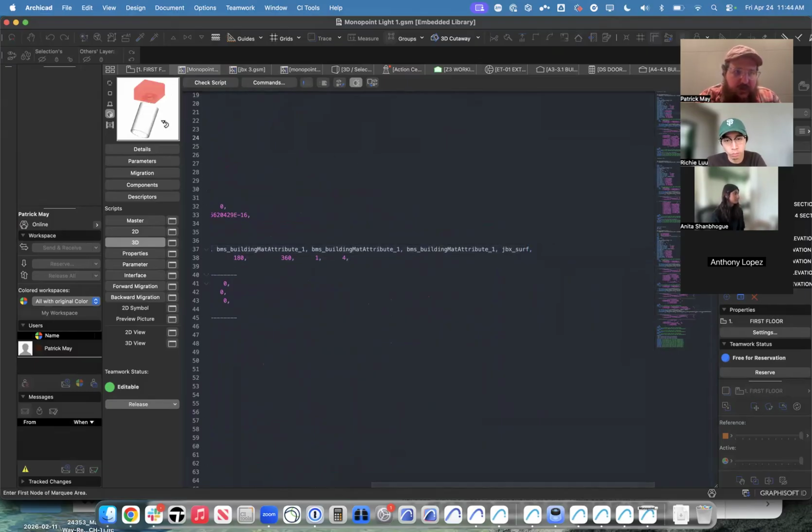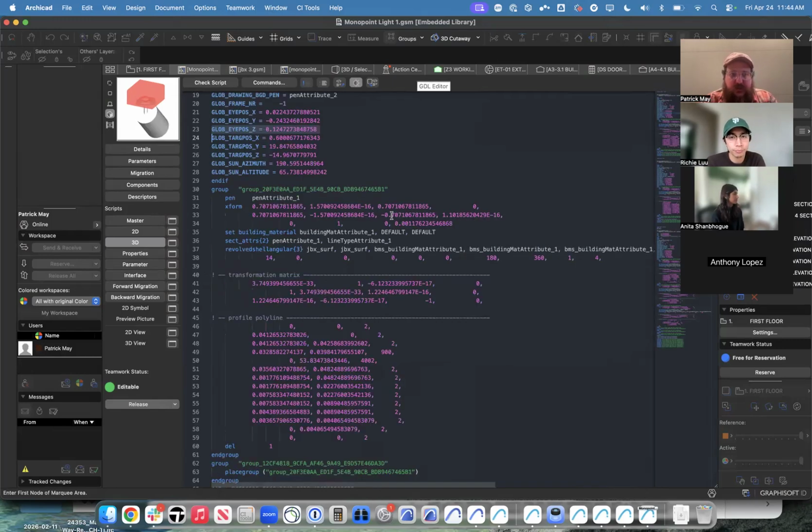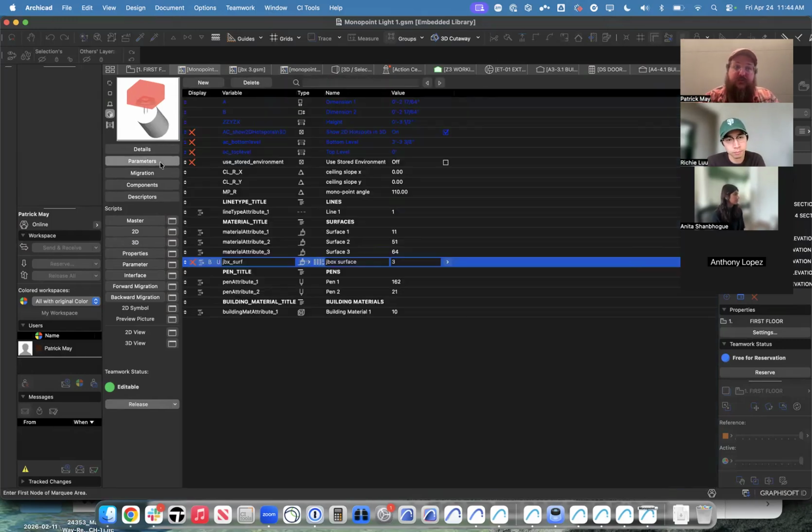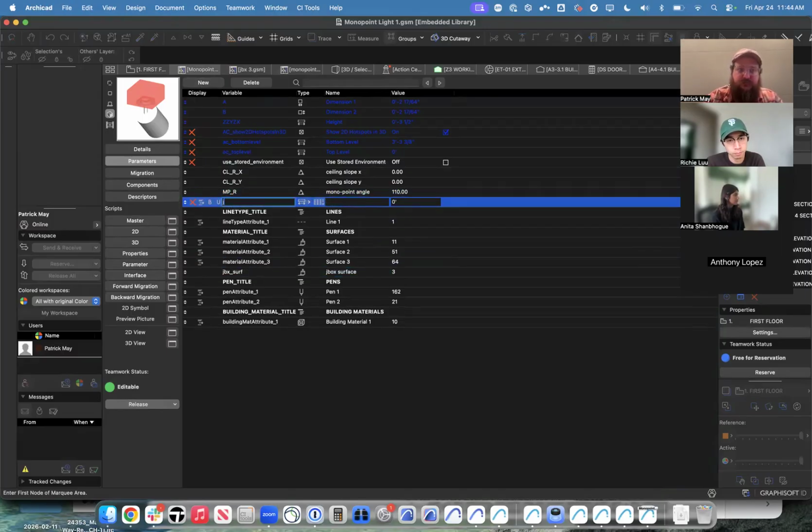Okay. So now looking there, we've got that as a red jelly. We could do the same thing we did before. If that junction box needs to have an on-off command, we can say new JBox on off. We'll copy that. So the variable, what you name those, it just has to start with a letter. It can't start with a number, and it can't have any special characters. I believe that even includes dashes. It's okay with underscores, but not dashes. And again, we'll make that a Boolean function, and we'll say JBox on off.